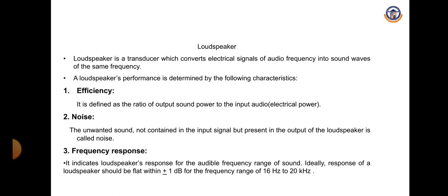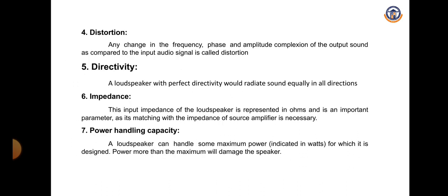What is frequency response? It indicates the loudspeaker response for the audible frequency range of sounds. Ideally, the response of the loudspeaker should be flat within plus or minus 1 dB for the frequency range of 16 Hz to 20 kHz. The next characteristic of a loudspeaker is distortion. Distortion means any change in the frequency, phase and amplitude components of the output sound as compared to the input audio signal.